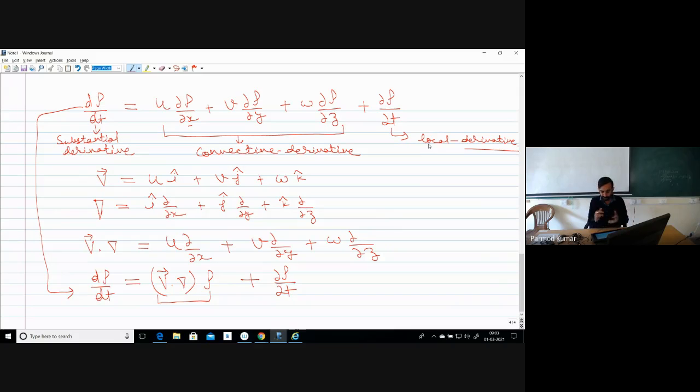So momentarily you got some more temperature, and once you crossed the door, the momentary effect of the heater or blower will not come, but obviously the effect of the convective term will come, and inside you will find it warmer. So the substantial derivative represents the total effect of the change in spatial location plus any local transient perturbation which is there in our flow field.